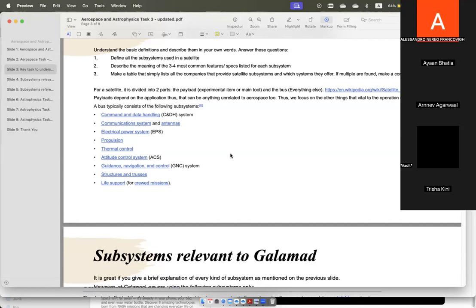Okay. So for our current mission, for example, we have a UHF antenna, and what we're using is just a tape measure. The literal tape measure, for those of you who have done some engineering, is for measuring distances and lengths. We cut that to the appropriate length, and it's an antenna.